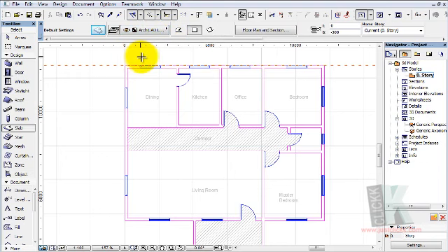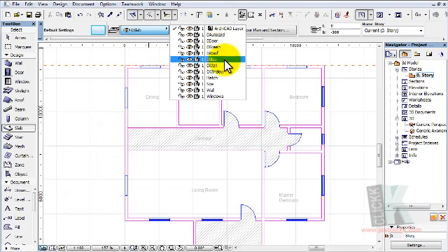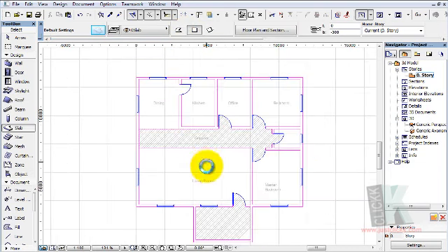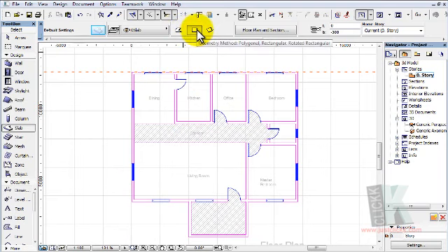So we already created a slab, so let's go to the layer here and pick the O slab, and you have the geometry method option here. That is the type of slab you intend to use. We are going to use the polygonal slab in this case. Otherwise, we could have used this rectangular slab if only this porch weren't available. You know, the building looks more rectangular, so we would have used that, but because of the porch, we're going to use the polygonal slab type.